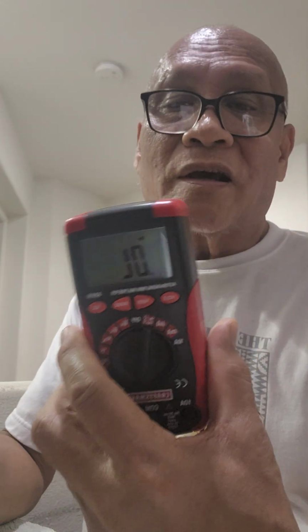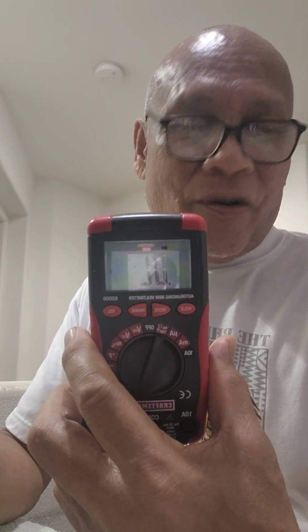Actually, I will just show you the last one. We'll try to reverse direction and see if there is a voltage drop. I will interchange the location of this one, the last one, the D4. Let's try to see if the diode will conduct. The diode will not conduct. It's an overload. It's an open circuit. Meaning to say, in the reverse direction, the diode will not conduct.